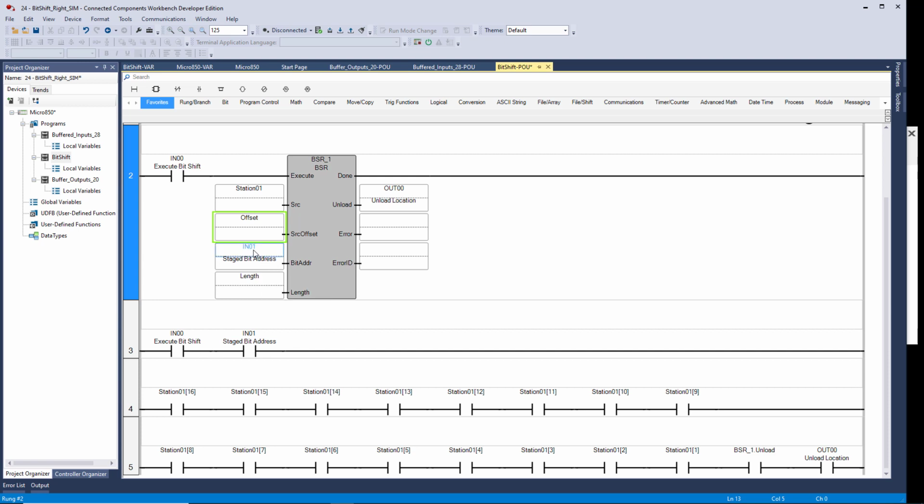So rather than looking up here, you'll see if we've got a 1 or a 0 staged to go into the shift register, because remember that wherever the first bit is in the length of 8, so if we're doing 1 through 8, then whatever value is in this memory location, when we execute, the shift register is going to take this value and move it into here.